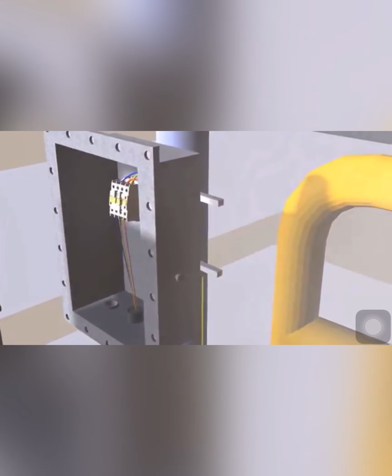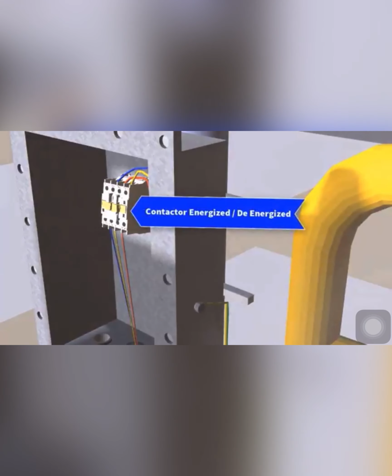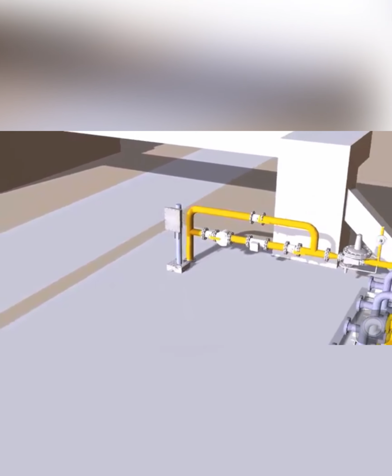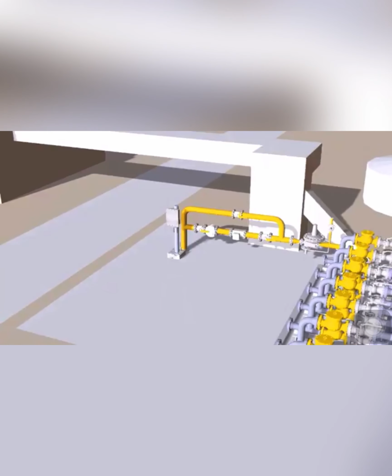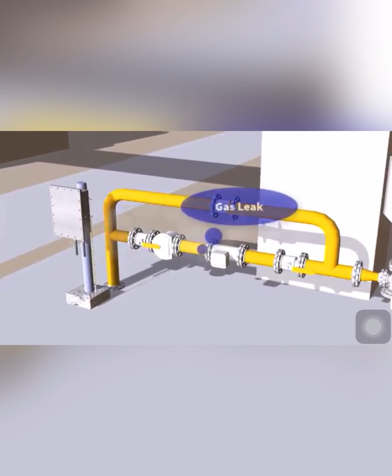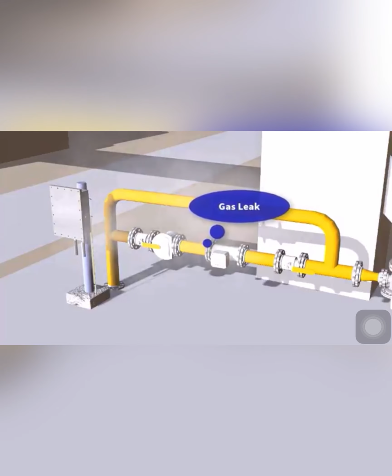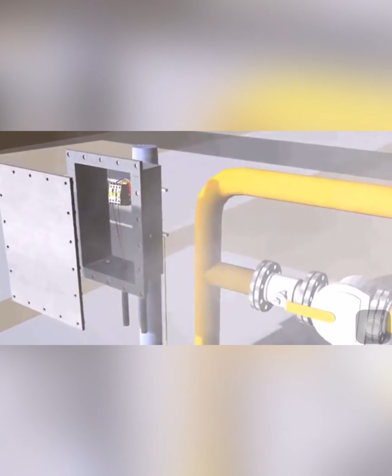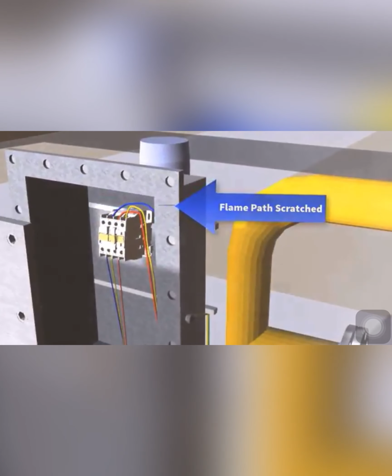For this reason, the measures available for such locations are limited to avoidance or restriction of flammable substances which are capable of forming an explosive atmosphere, and avoidance or restriction of release of the flammable substances and therefore formation of explosive mixtures both inside and around fittings by limiting their concentration, using enclosure filled with an inert substance, natural or artificial ventilation, concentration monitoring by means of a gas detection system which will give an alarm or switch off the system.